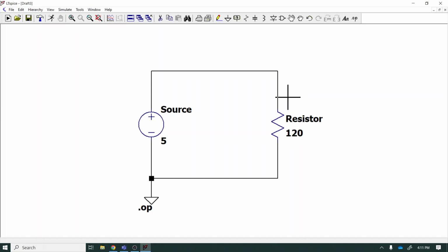And each piece of wire that has its own unique voltage has its own unique name as well. At the bottom here, you'll see this one is ground, because all of these wires are connected to the ground connection. All this will be 0 volts. Now it does just create the names of these nets itself. It's called this one N001. You can give them names yourself, which can be useful for more complicated circuits.